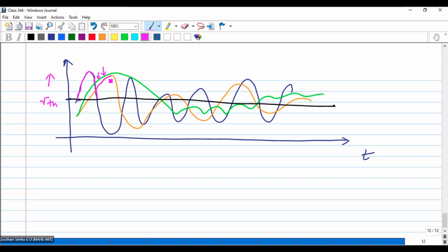Now, if I come to this point, I have followed this branch because there is no other alternative branch. Though in selection combining, I might have gone with this because of the highest possible SNR. Here, I don't have any other SNR. I'll have to come back to this lower SNR and I'll have to switch over here.